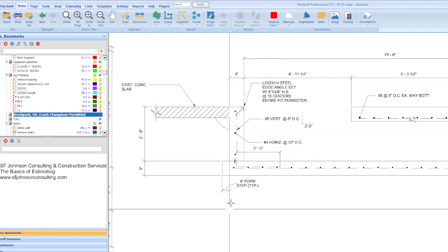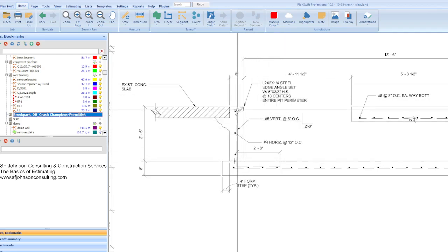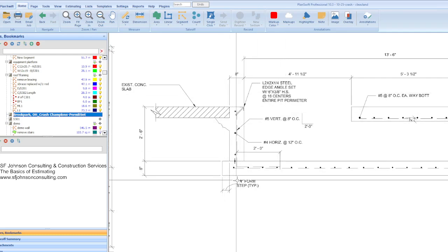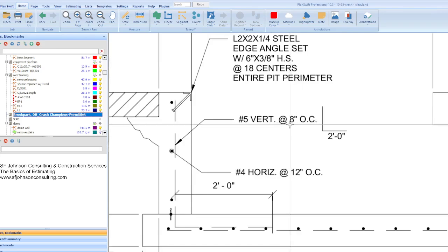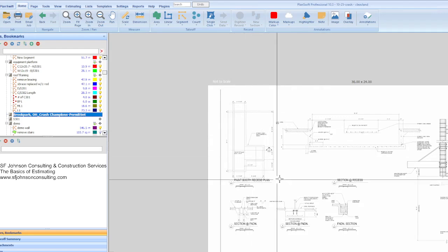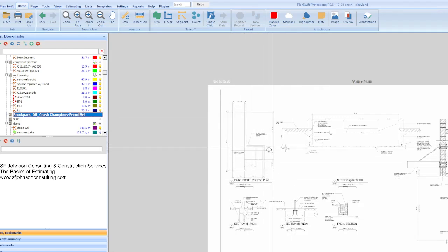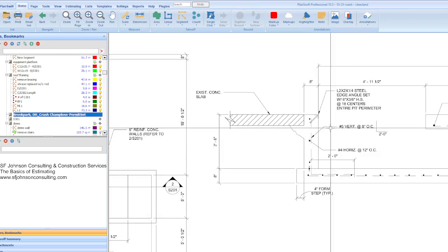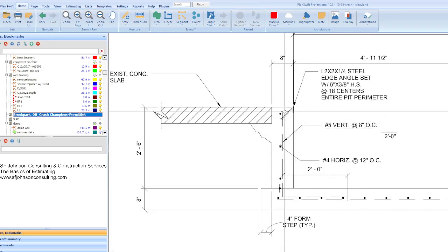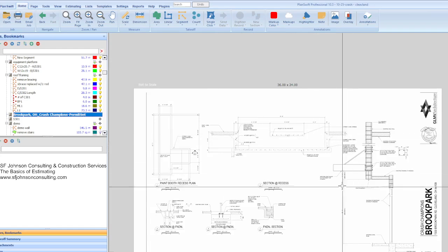So the vertical is the up and down conduit. So you have to say, well, it's that many linear feet, and it goes the whole perimeter too. So that many linear feet at the 8 inches. So what's the perimeter? However many linear feet, change it into inches, divide by 8. Then you have that many placements times the length at each placement. So really easy to do.